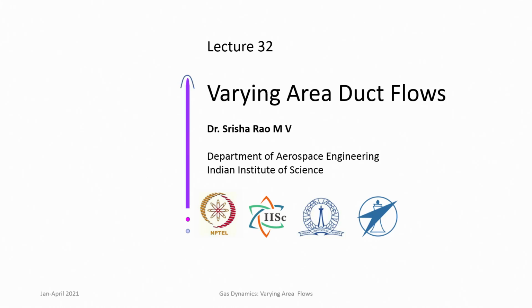Similarly, if you increase area with an incoming supersonic flow, then you find that velocity increases, or it behaves like a nozzle. So, a divergent duct is a supersonic nozzle. This is the behavior one has to always understand and keep in mind when we discuss varying area ducts.